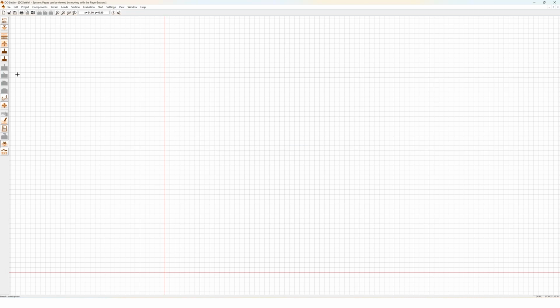Then we can enter the soil data. Here we have a groundwater depth at 100 meters, so it won't have any influence on the calculation. Then there's the opportunity to enter a correction coefficient kappa. This is not state of the art anymore. It belongs to an old standard, so we don't apply any smaller values, and it stays 1.0.